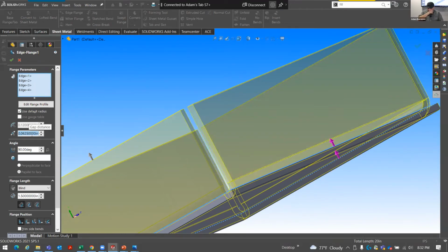A lot of times what that is determined by is your spring back in your sheet metal, right? Because once you bend a piece of metal, you have to overbend it, take it past its yield point, and then it's going to spring back and be at its location. So sheet metal or press brake operators get your information and put those calculations into the press brake, make that first bend, and then put it on the gauge and plus or minus whatever they need to add to that angle, because they're not going to bend it at a 90. They might bend it at a 95. They may overbend it a little bit or underbend it a little bit, depending on the spring and the steel. Okay.